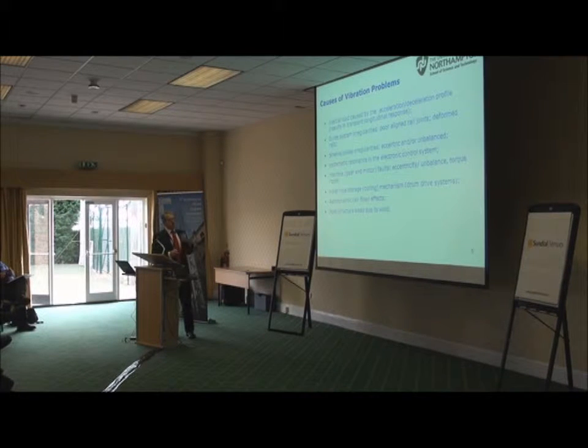In some cases, in older lifts, when we had a drum, there was a coiling mechanism which could cause vibration. Now those lifts do not exist, but for the record. And also we have aerodynamic effects. When the lift car moves within the shaft at speed, we have turbulence, and this is causing force, which is acting upon the entire system. And last, not the least, we have the sway of buildings due to the wind or earthquake.